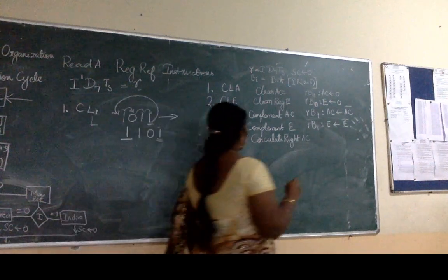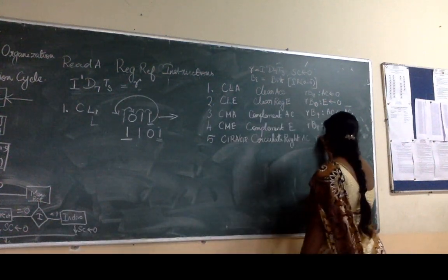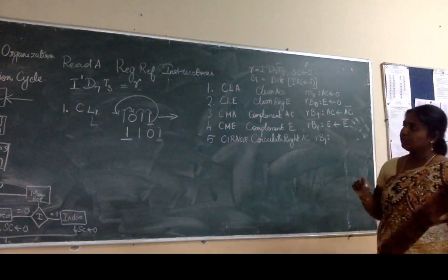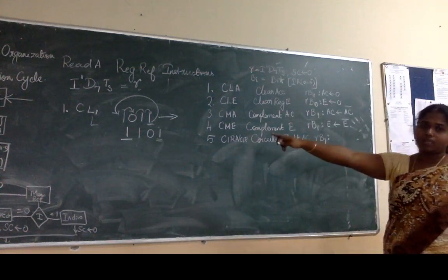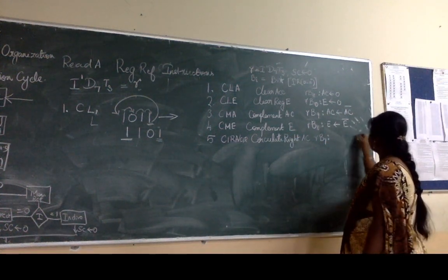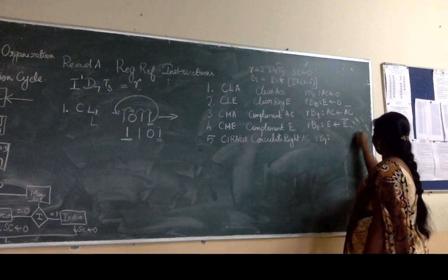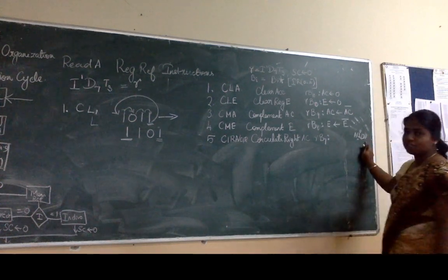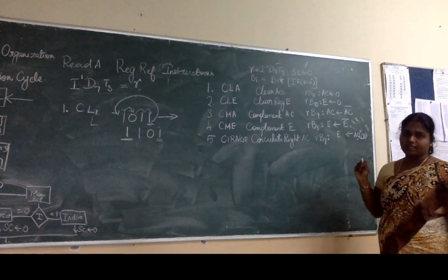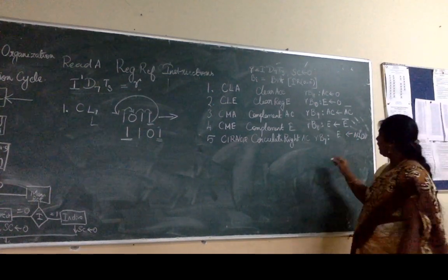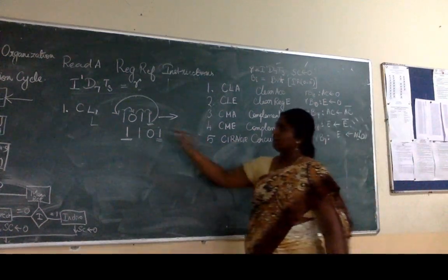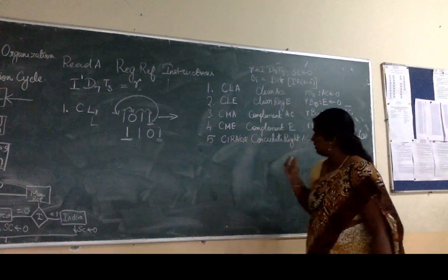So, this can be indicated as RB7. The first thing that I do is I have to safeguard my LSB. The LSB is the 0th position of the accumulator. The 0th position of the accumulator is pushed inside the extra register. Then I perform a shift right operation. Shift right operation is nothing but moving everything one bit right side.